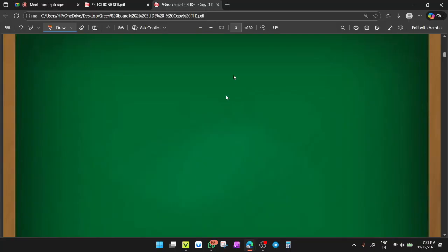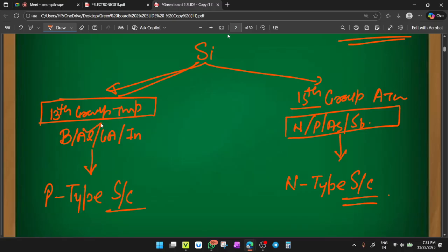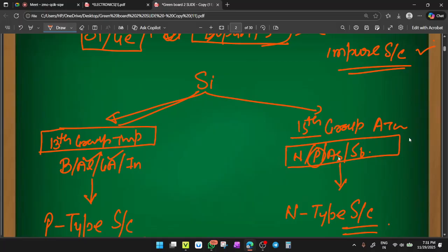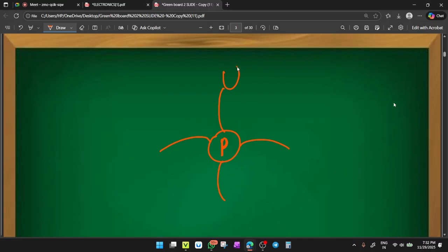Yes, first understand this. What is happening there? Like there is an impurity atom, you have added aluminium or boron. Okay, sorry, we are talking about N-type, so we have to take phosphorus or arsenic. As it is the 15th group, in the outer orbit there will be 5 electrons. So check here, this is the phosphorus. Let us suppose we have added phosphorus or arsenic. So there are 5 electrons in the lattice, 5 free electrons there. Silicons are there to make a bond with the phosphorus that is the impurity. You know the valency of silicon equals 4.